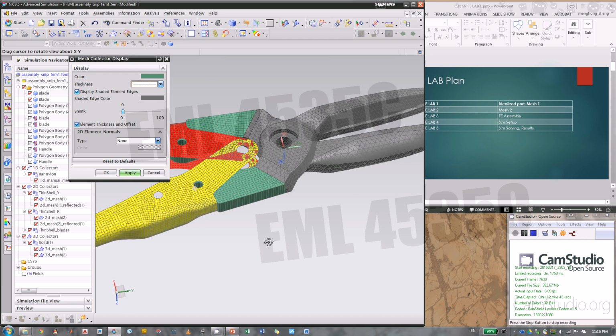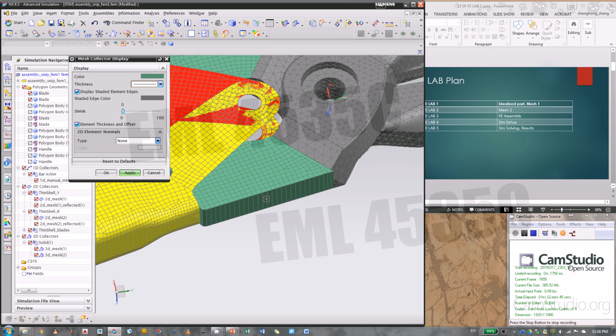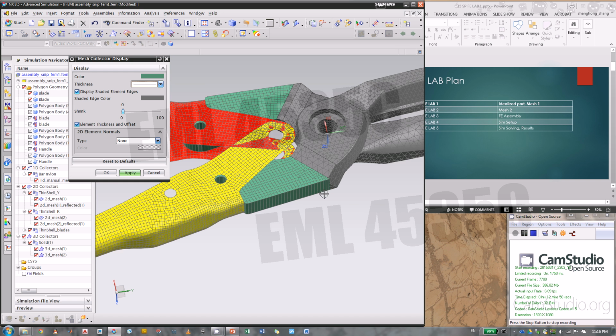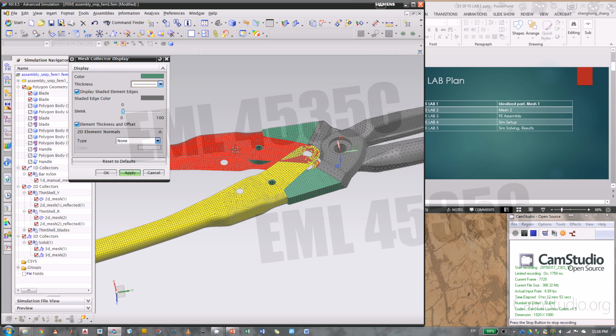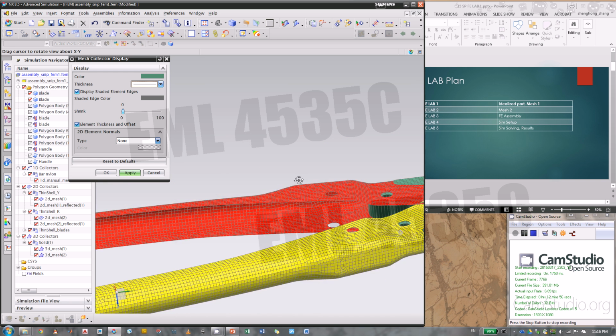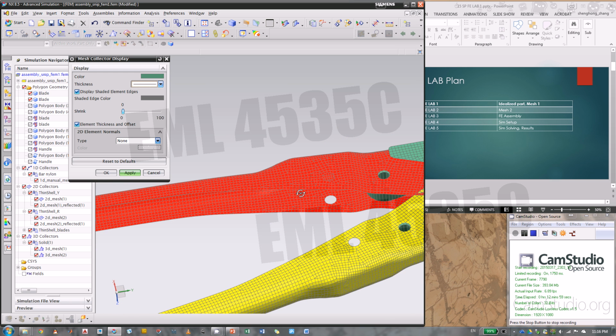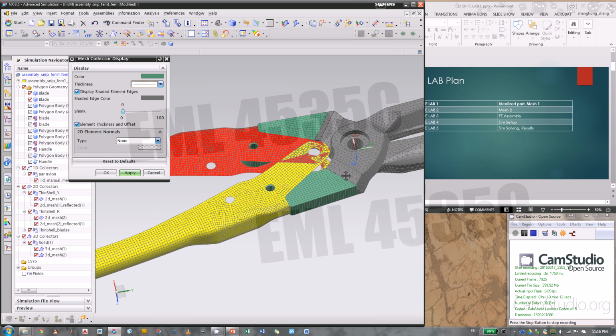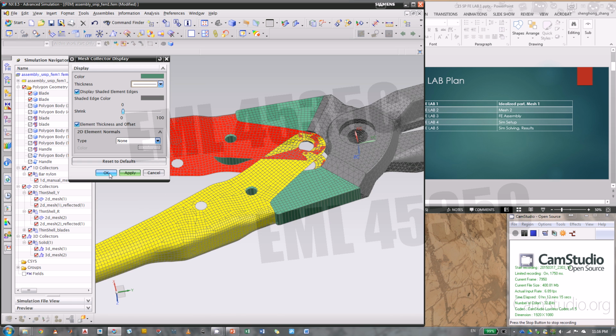By default, the thickness of a 2D shell goes symmetrically. Your shell is in the middle. That's why we need to find the mid surface of the handle. If you just mesh the top surface of the handle of your 3D geometry, your mesh will be offset by half of the thickness. So that's the reason we use mid surface.